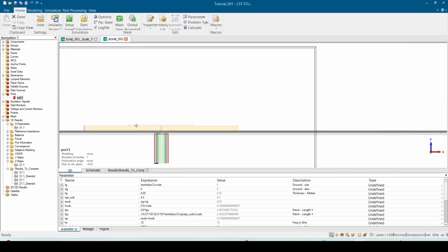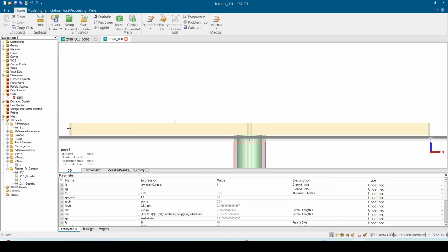We can discuss in the next video that when we scale up, we have the potential to have more bandwidth compared to the low frequencies, because we don't actually have to scale the substrate. We have one substrate, and we want to make it work for all frequencies. If the patch is smaller because the frequency is higher, the patch now looks bigger, or the substrate looks bigger, which means the bandwidth could be higher.